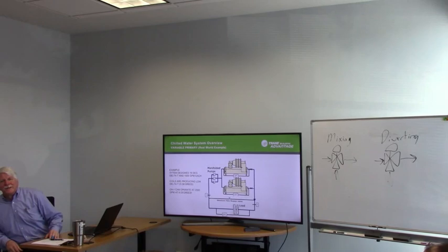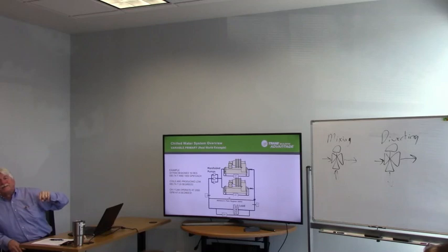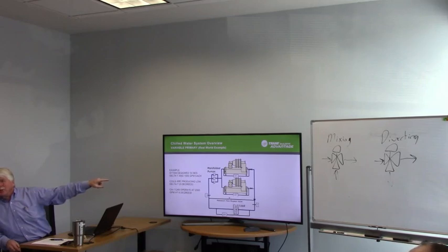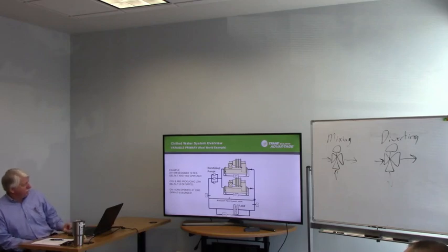So it's very low delta T on the system. But the real cool thing is, those chillers are kicking butt and taking names because they're running at about 1800 GPM at a low delta T. So you have to look at what both sides of the system are to understand how it's operating.